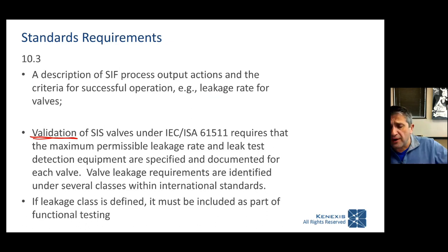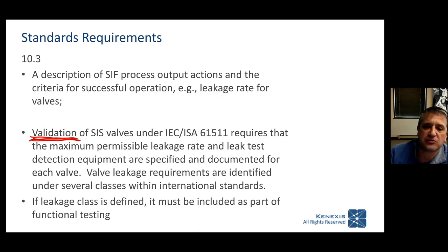So you put on your hard hat, you go out to the field, you find the valve, and you've got your data sheet, and you should use a data sheet for the valve. I'll explain later. And then you start checking off all the items: make and model and direction and all those settings, things that you can visually inspect to make sure that it's correct. But when it comes to leak tightness, you're going to need to actually perform a test. So for validation, if you say that the valve needs to achieve tight shutoff, you need to test it to make sure that it actually is tight shutoff.